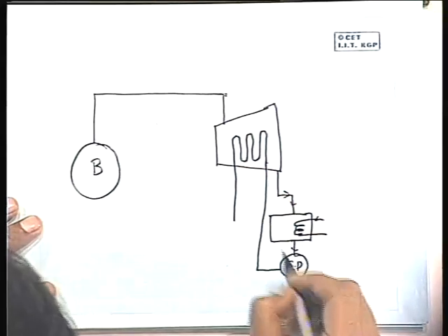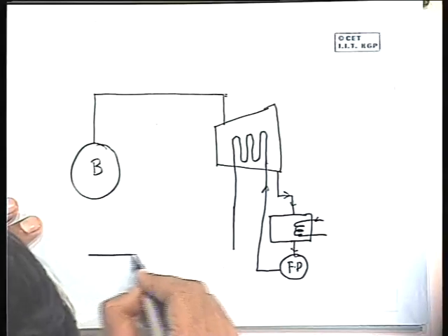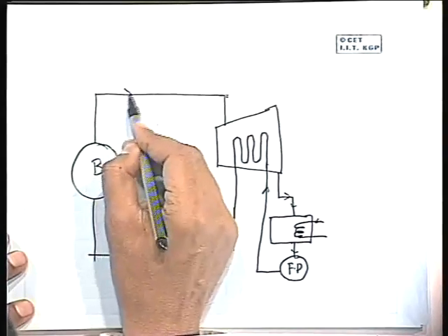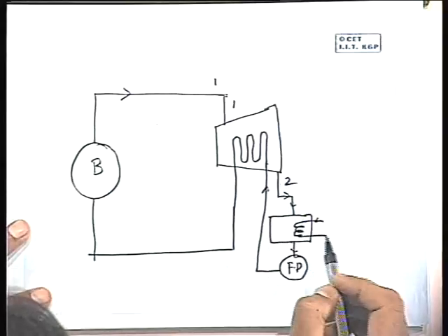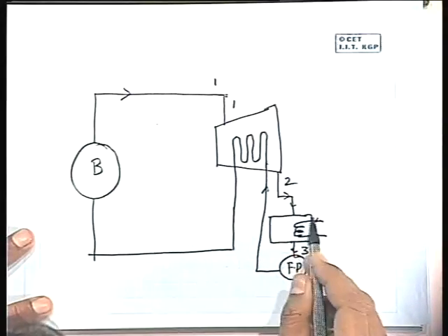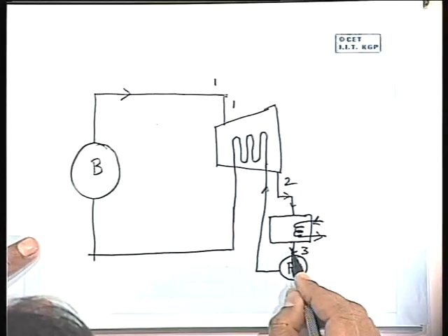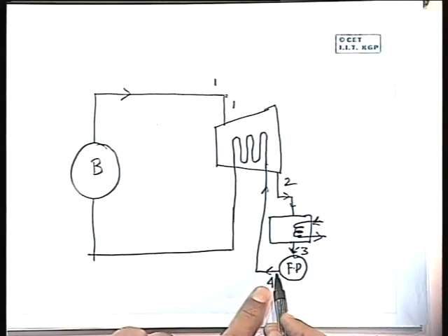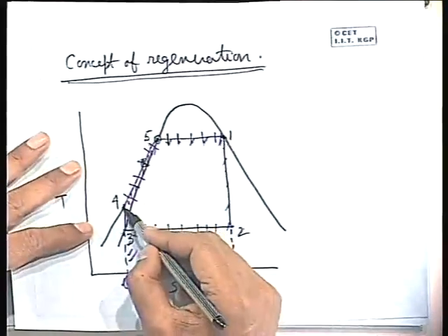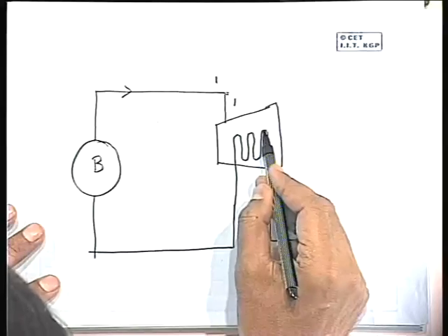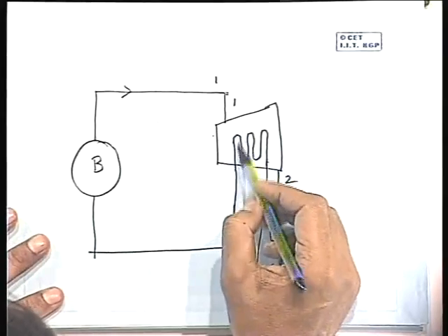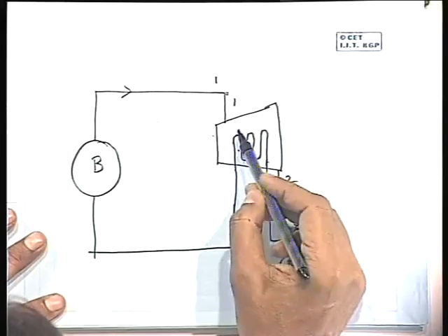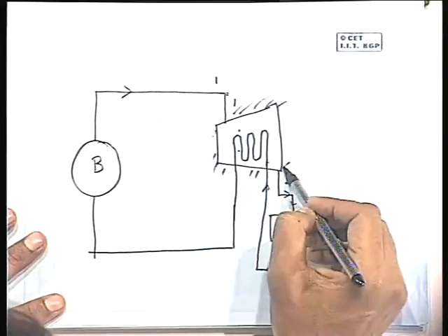A heat exchanger, that means this feed water is heated and then we give it to the boiler. Try to understand: the turbine inlet steam is expanded to the point 2, then it is condensed to the point 3 in the condenser, where heat is taken away by the circulating water, then the feed pump raises it to 4. If I don't heat this water, that means if I feed this water 4 to the boiler, what will happen? I will have to heat up from the point 4 to 5. But instead of that, I place this water through a coil in the turbine where the steam is expanding, and let heat transfer take place between the steam and the water, so that the water takes the heat from the steam. The entire turbine is insulated, there is no heat transfer with any third body outside.